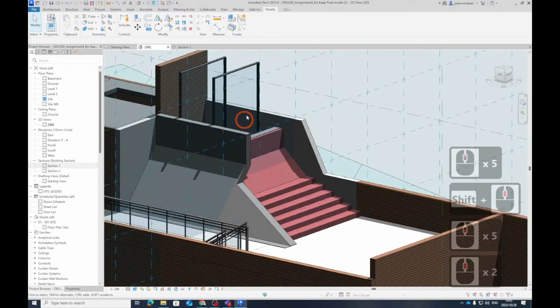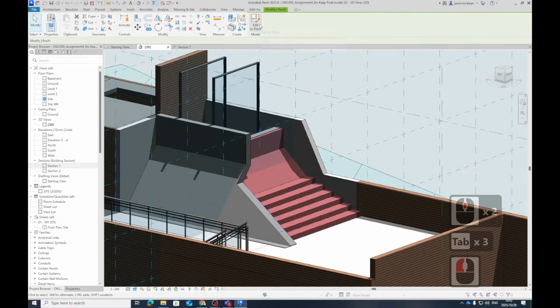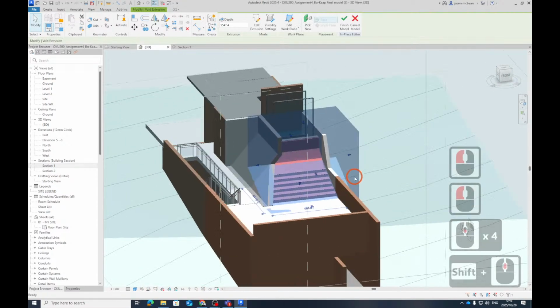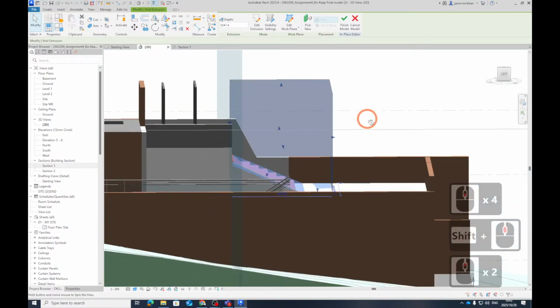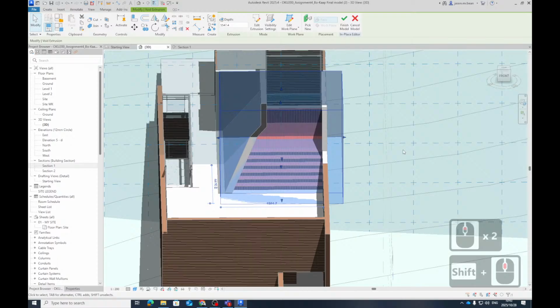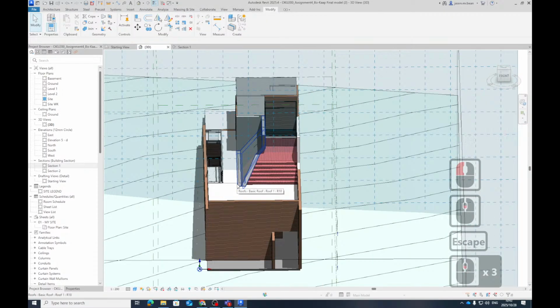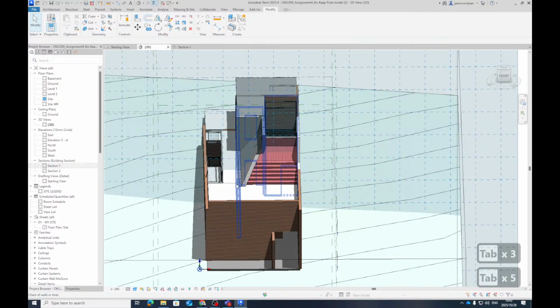But all that you've got to understand is, if you tab once or twice, you select where it's cutting, then you have to go and say edit object. And it's always invisible because it's cutting something. So tab, it's like, how did you do that? So what tab does, now I've got a whole lot of objects overlapping, if in the view there's a lot of objects. Look what happens when you start tabbing. So if you move it a bit, tab, you see it'll start cycling through. And at the bottom here, you see, it tells you what's selected.